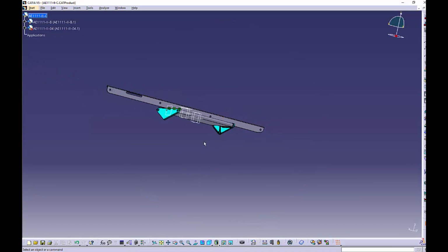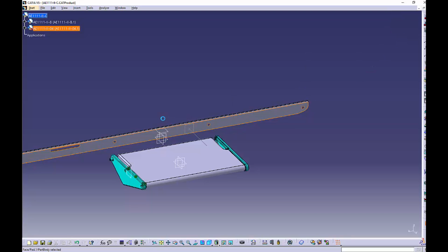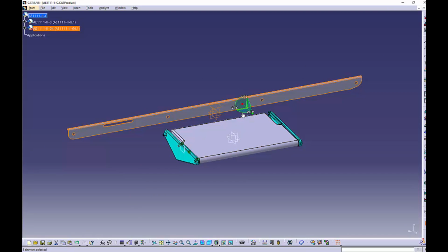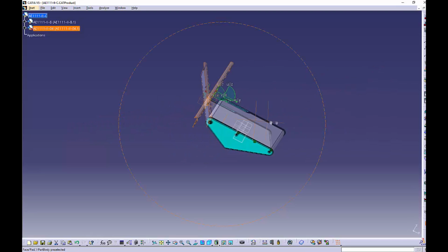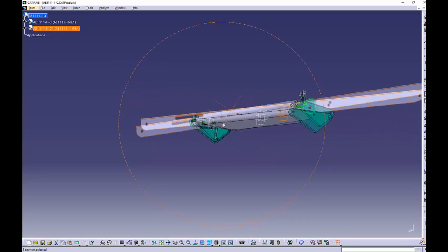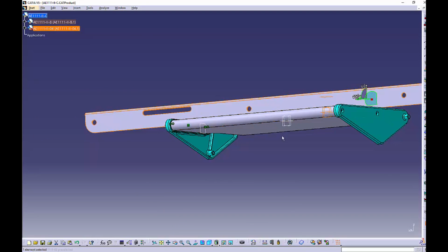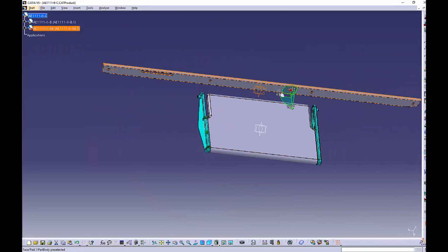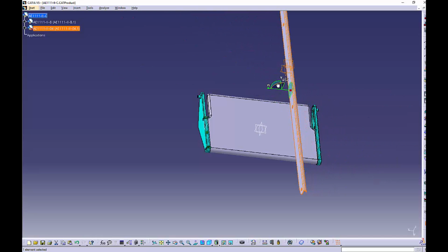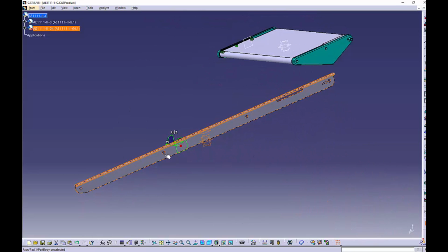So we will move it with the compass, so it gets a little bit clearer. Select your compass, drag it on it, select your object, and turn it. The inside is in our object where the arrow side is, and the outside is this side. So the outside should touch this wall of our stair support, and the inside, the arrow side, should point to the middle of our stair inside. So we turn it like this, and then we turn it and drag it a little bit to the back, a little bit down, and a little bit to the left. No, that's not the left.